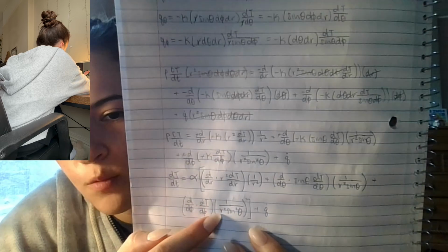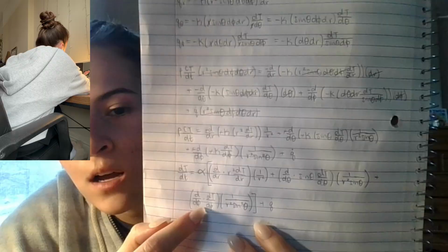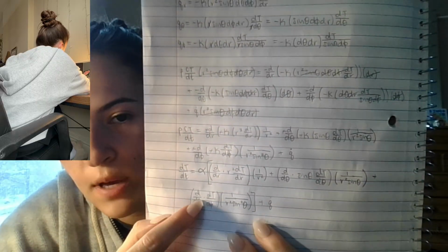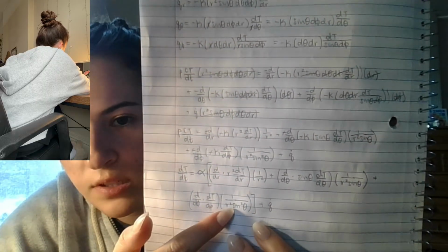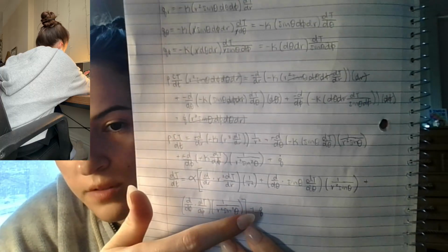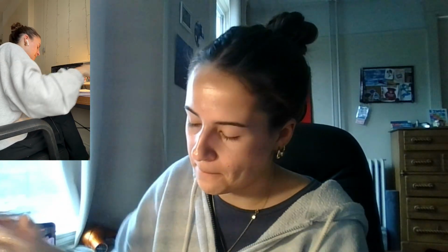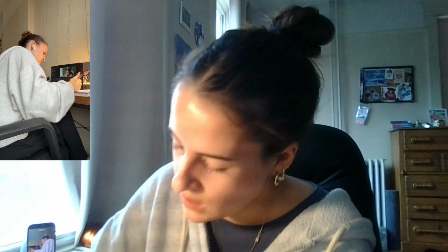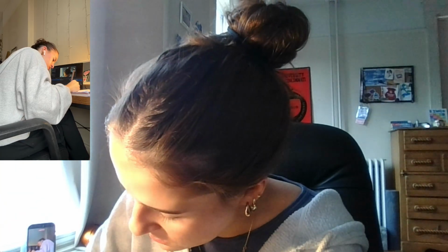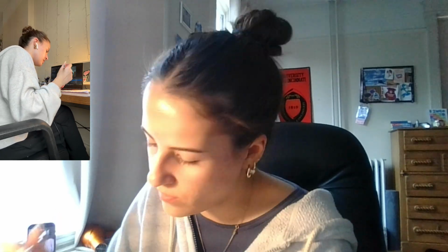And then here, we actually could simplify this into our second derivative of phi, because we don't have any phi in here that we have to evaluate first. And then this was the additional from that here. And then on the outside of everything, not multiplied by the thermal diffusivity, is our energy generation term, which is just q dot now. So I'm going to go ahead and rewrite this to make the phi term be the second derivative of phi.